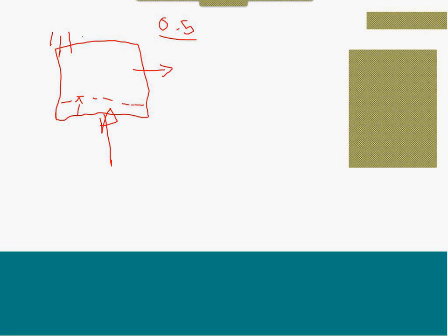Assuming we are holding it over here, the part needs to expand in these two directions. This is the ideal situation wherein I have a unit compression in a certain direction and it is absolutely expanding in the other two directions, which is 0.5. Anything below 0.5, it is not absolutely expanding, and this is where we are answering the question: yes, the volume would change if Poisson's ratio is below 0.5.